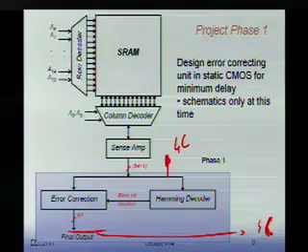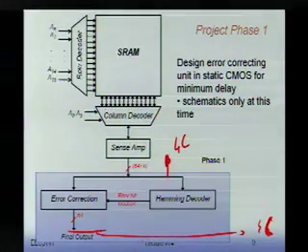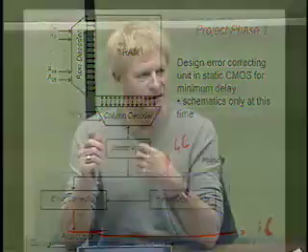Not much fan-out. The real problem is going to be sitting in fan-out factors here internally, and how you design this thing. So that's really what we're trying to do here. So first thing you do is you look at the problem, start playing around with different schematic diagrams. What's the logic you would use? And then you can imagine already here 64 plus k parity bits. You're going to start with some XORs, right? Because Hamming code decoder, this thing is a bunch of XORs. And how many input bits do we have? We can know that too, right? 7 input bits. But I'm not going to say anything more than that. The rest is for you to basically figure out.